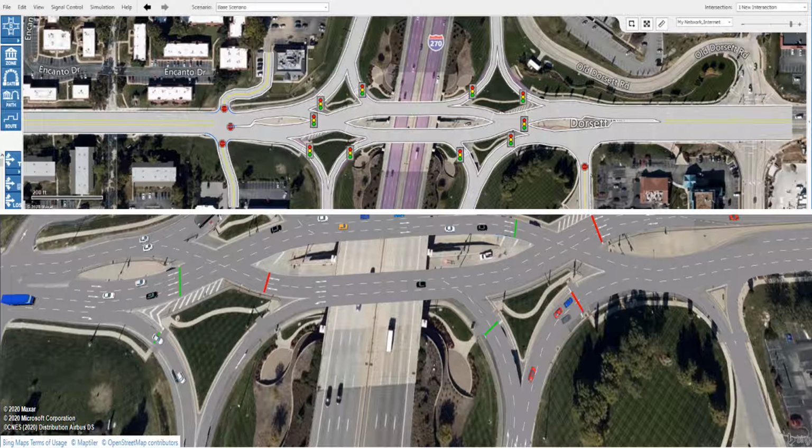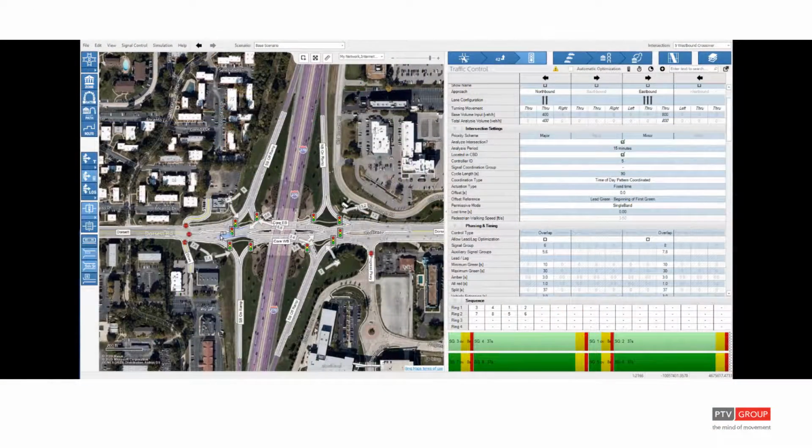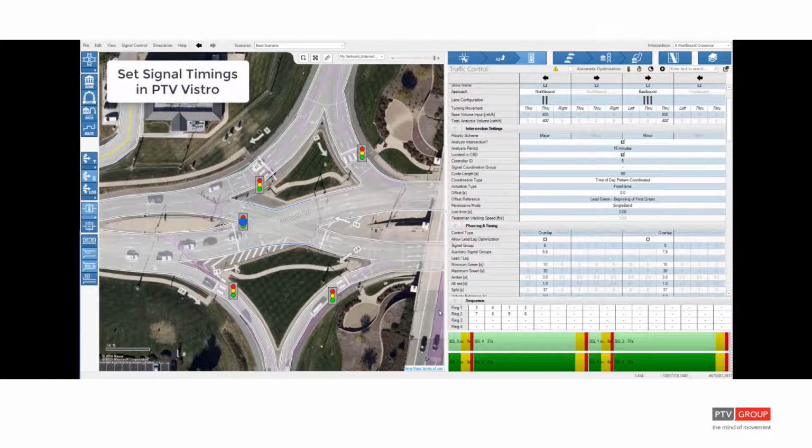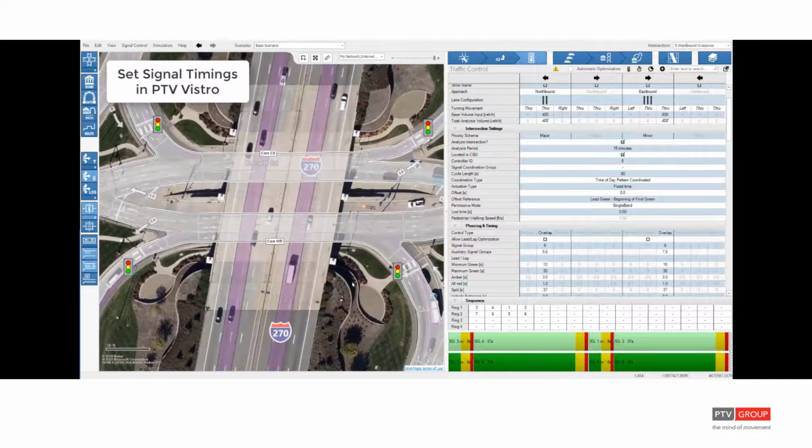And then one other fun fact about DDIs, since it's pretty much broken into one-way legs anyway, the resulting Vissim layout is a pretty nice layout. So on this video, you can see that step 1 here is that you would kind of test your MOEs and see how this DDI behaves. Maybe you'll change some of the signal timing as you go through here. You can go check the other terminal here, and by checking the other terminal, then you can verify if it's all right on that side.